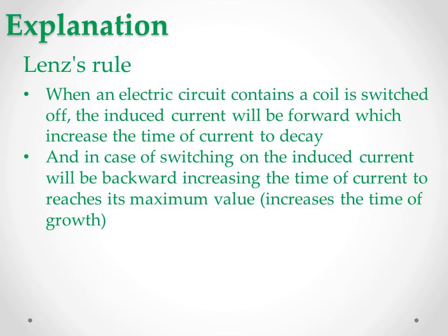Explanation. Lenz's rule. When an electric circuit containing a coil is switched off, the induced current will be forward, which increases the time of current to decay. In case of switching on, the induced current will be backward, increasing the time for the current to reach its maximum value, which increases the time of growth.